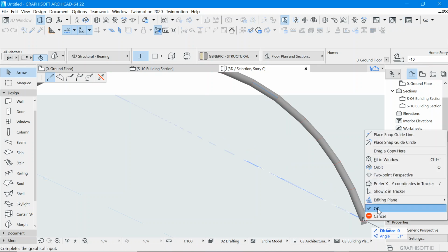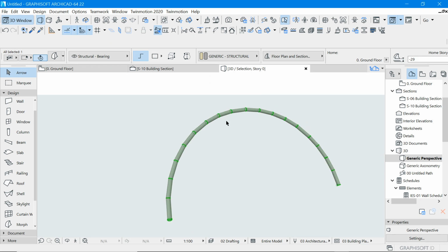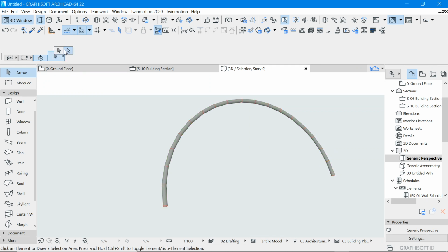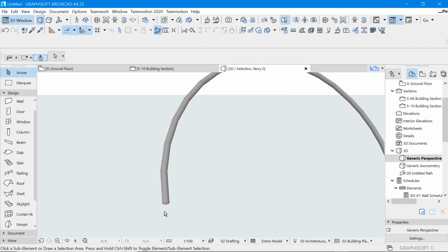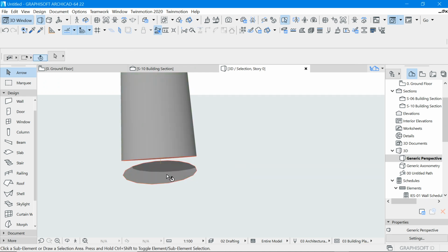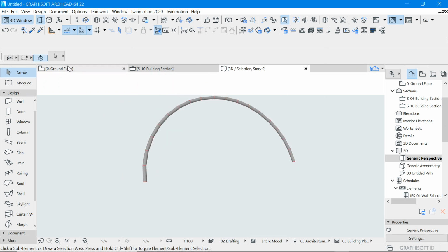Then at the bottom say OK. That looks fair. So with this morph done, you just click, then enter into edit mode. Come and remove this bottom bit, even this one, even this up down. So what you remain with, you get out of edit mode, click on it.